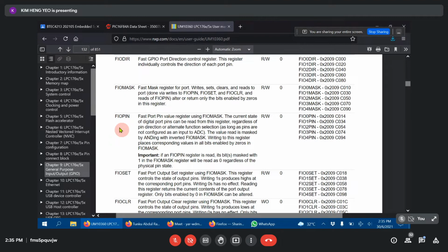But right before you scoop, you get interrupted. The noodles then went and did something, and changed to become rice. Then you continue with what you were doing. You scoop, and then you eat. When you eat, why is it rice? It's not noodles. Because the data can be changed by other processes. If they interrupt you and change what you're doing, then what you're doing might become wrong, right? That's why you have FIO set and FIO clear on top of FIO pin.